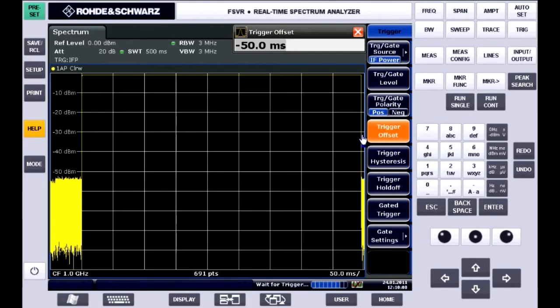Now from this view I can see the output power is nice and level. It should be, this is an FM transmitter. And then we can also use markers and measure that pulse width. If we do, we'd see it's about 450 milliseconds. But I can't see any frequency dynamics in this view at all. So if there's any settling time going on or any frequency error, it's invisible to me in 0 span. So that's where we go to the next step.